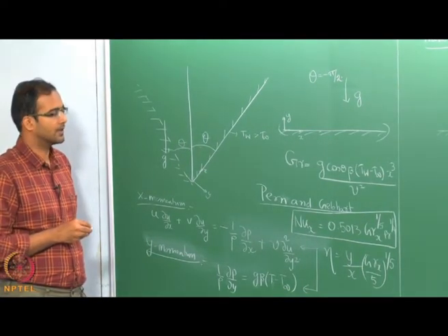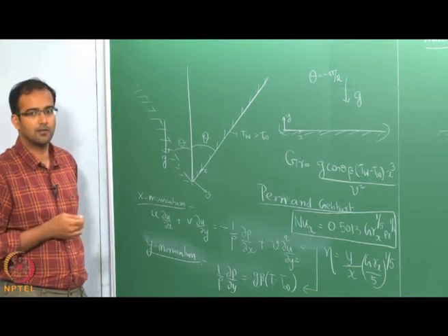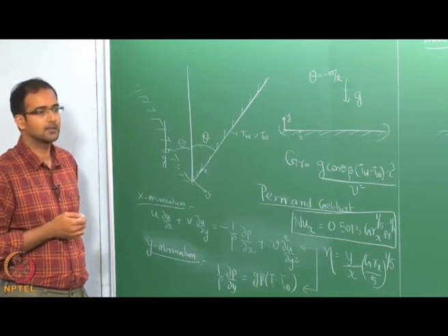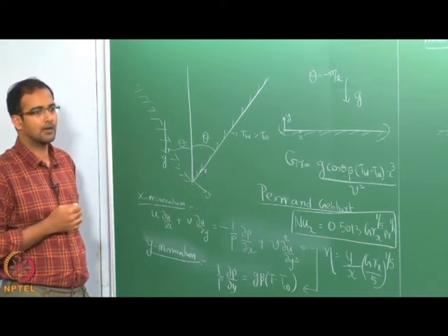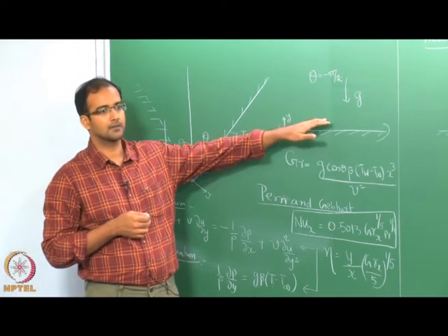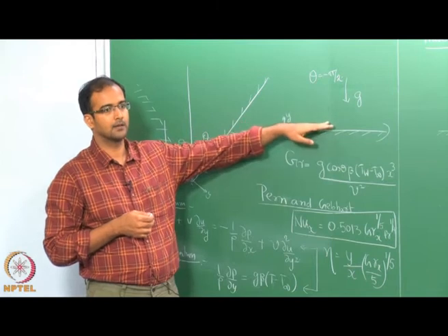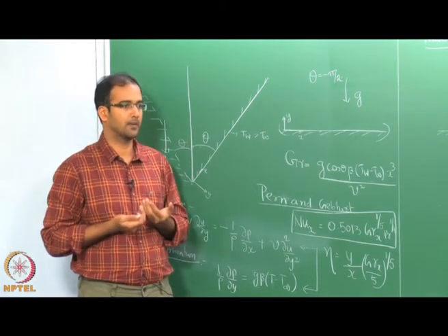Of course, you have to do a finite difference or finite volume method based solution in order to solve this exactly. You cannot neglect also the vertical momentum. There will be some streamline patterns which will arise due to the buoyancy in the vertical direction and that will definitely cause some vertical momentum.